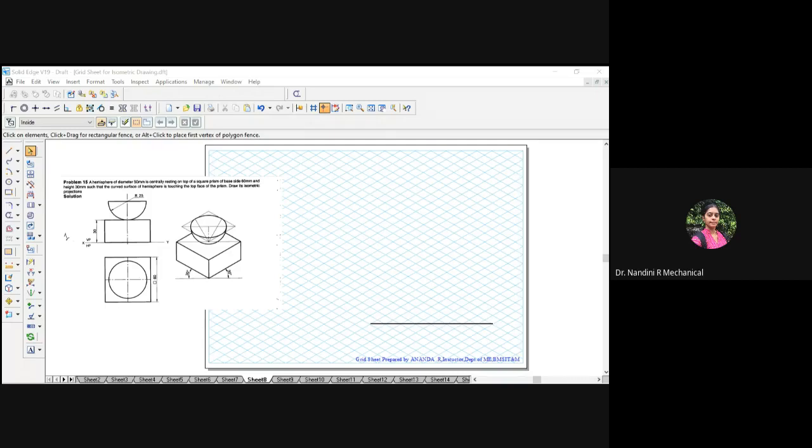So you get 48.98 mm. To get the number of counts on the grid line, divide 48.98 by 0.8164. How much do you get? 6 is the count. So you have to take 6 towards your right and 6 towards your left.